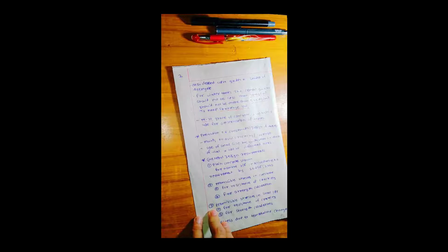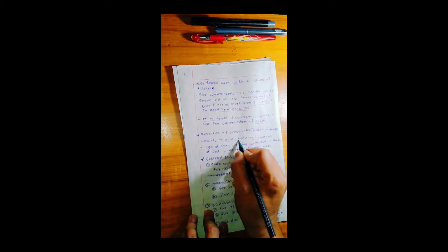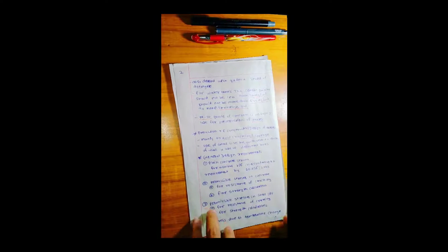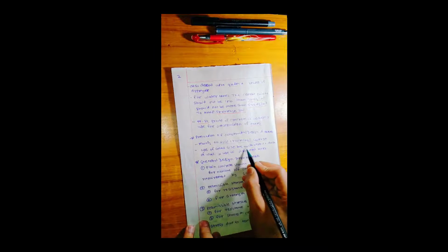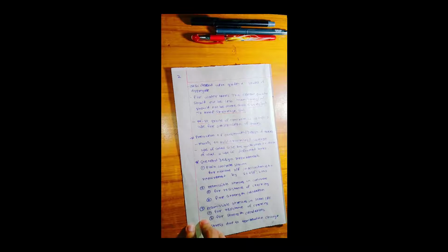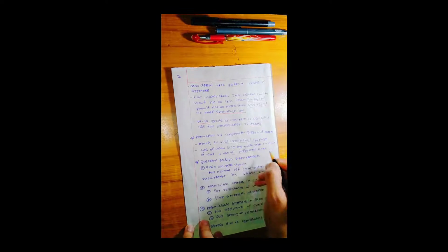The main attention is that we have to avoid cracking or leakage of the water tank. If there is a leakage then it is very hard to repair. Use small size bars with respect to the thickness. If we assume the thickness of the water tank wall as 100 mm, we cannot use a 16 mm bar as reinforcement. If we go for 200 mm thickness then we can use 12 mm, 10 mm or 16 mm bars. Use deformed bars for the reinforcement.